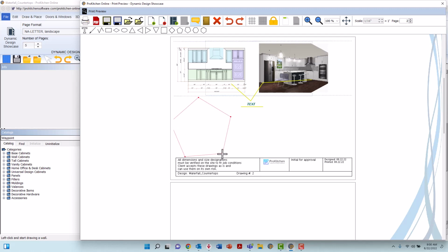You may rotate the shape by moving the mouse in the direction of the desired rotation, being mindful that any comments added will also be rotated. To enter the text, you must access the shape's attributes, again via the right-click menu or with a double left-click.